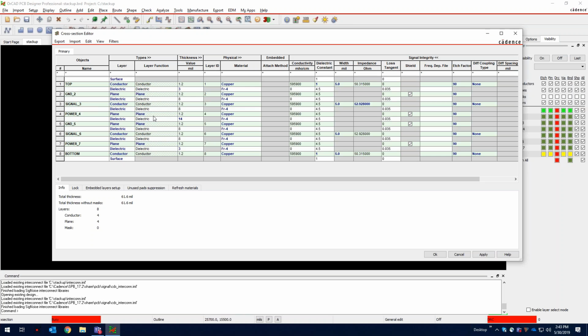Next, are the internal routing layers for high-speed signals? Here you have internal routing layers, and they are between the planes so they can be used for your high-speed signals. This will help minimize the noise. Now, are the signal layers closely coupled to the planes to help provide a good return path for your high-speed signals? Here the outer layers are closely coupled, but the internal layers aren't really as closely coupled to the plane layers. So this could cause some issues down the road.